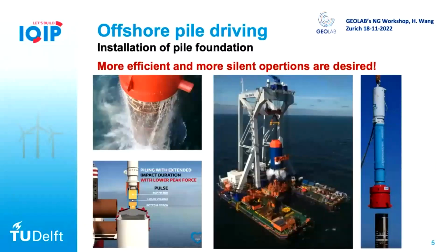So back to the monopile foundation, I think the first thing we need to consider is, okay, how are you going to install the monopile foundation? Because the monopile is quite different from the old piles because it's very huge. The diameter can go to 10 meters nowadays, and people are talking about 15 meters. And the embedded length is quite shallow, less than 5 times the pile diameter.